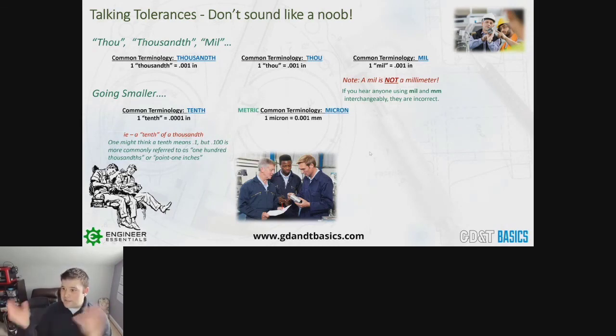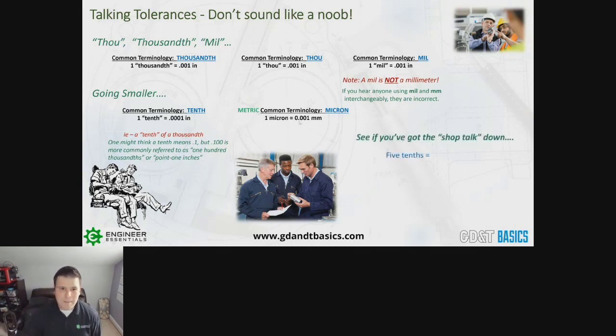So going into metric, very easy, microns. If you're dealing with tight tolerances and things like that, you have millimeters when it's bigger than a millimeter, but you have microns when it's under a millimeter. Even when it's 0.2 millimeters, it's usually better to say 200 microns because we're usually dealing with that level, especially if you're in the automotive, aerospace, biomed, those type of tolerance places.